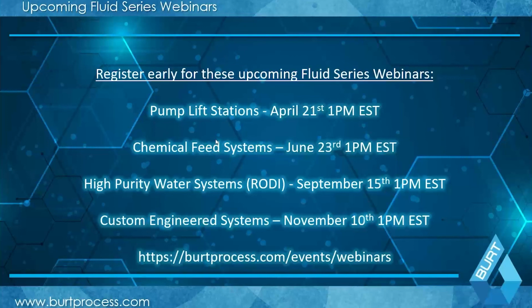So the question is, is there a limit for flow rate or pressure for the system that is required to not exceed for calculations of pH? pH systems are generally atmospheric, so pressure isn't so much of a concern, unless you're obviously going to be pumping into it at some extremely high pressure. Barring some unusual designs, pressure is not a huge concern in the pH neutralization system.